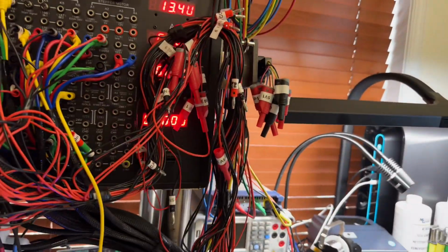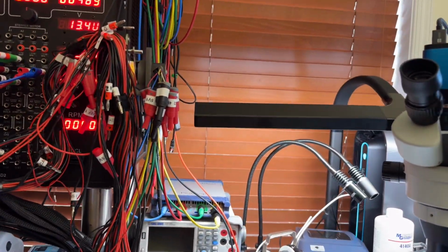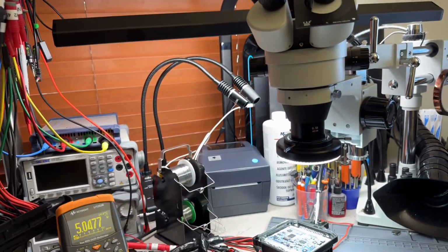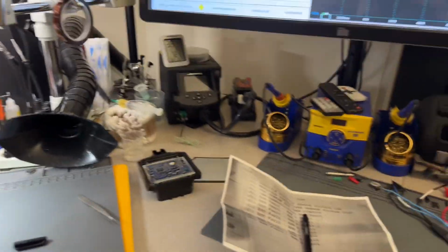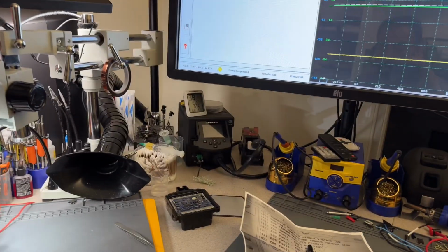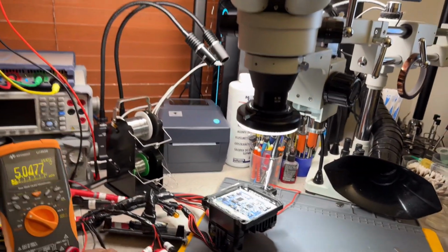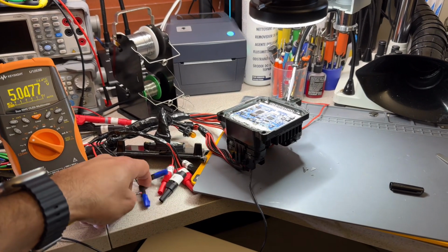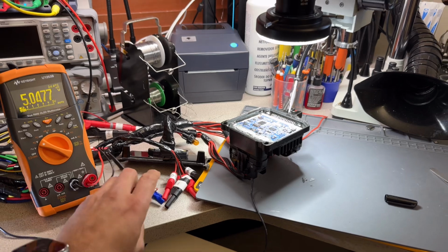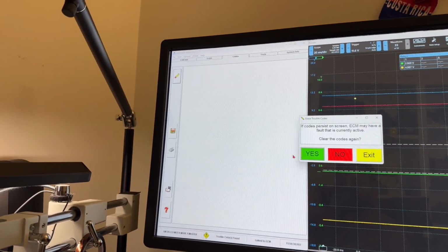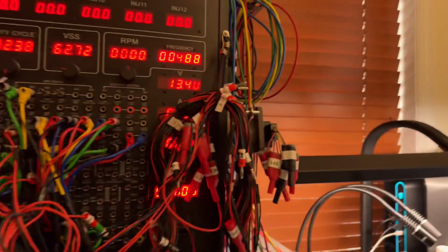So what I'm going to do is, again, turn the boat off. We're going to disconnect H, right? So now we know the H disappears, so H is good. We're going to keep F disconnected because that's the one we know already is good. And I'm just going to move this to the other connector that I have in here. We're going to reset the faults, and we're going to run the boat once again.